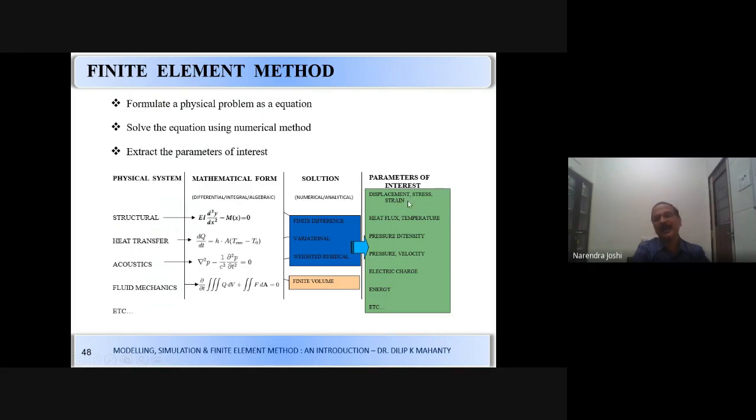Depending on that, how long this component or structure or product will be sustaining. We talk about, for example, a bridge structure being sustained for the next 50 years. How do I calculate that? When we go through the structural analysis and find out the displacement, stress and strain, based on that we find out how many cycles of stress and strain it will be able to sustain till the structure fails. So 50 years, 60 years, sometimes 100 years.